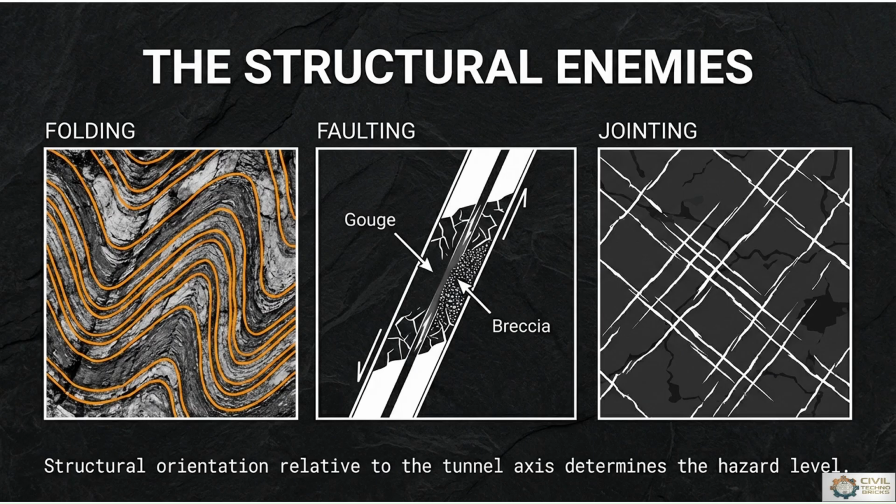So stable rock formations minimize support cost and improve tunnel durability. We are planning the tunnel for 100 years, so it must be durable. We have to prevent the structural enemies which are impacting it. Proper alignment reduces excavation difficulties and improves operational safety.